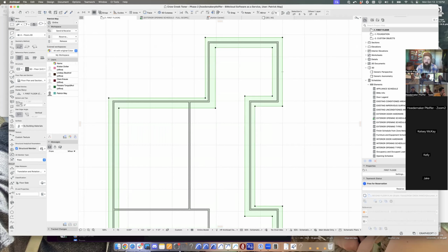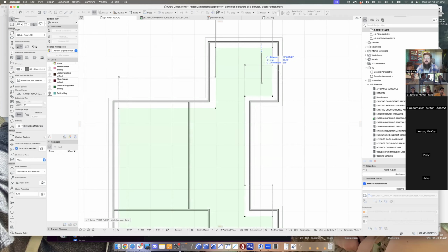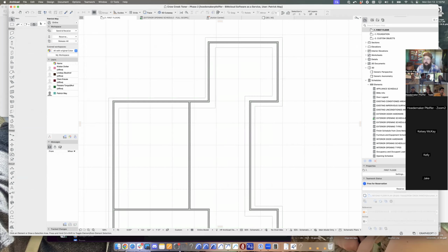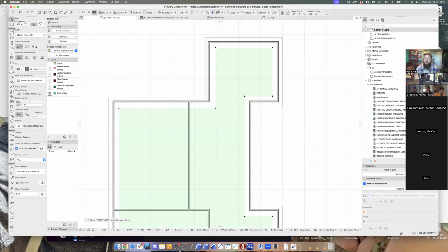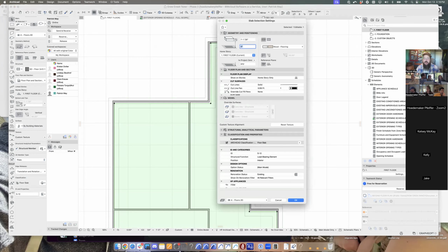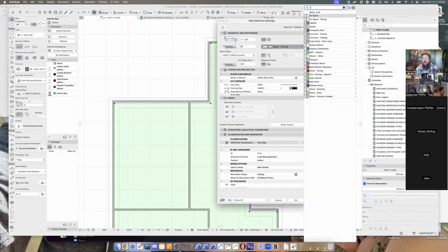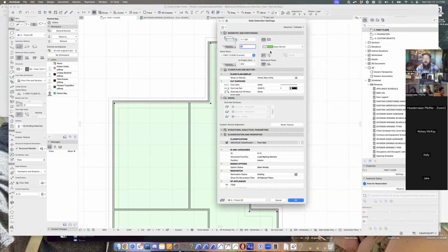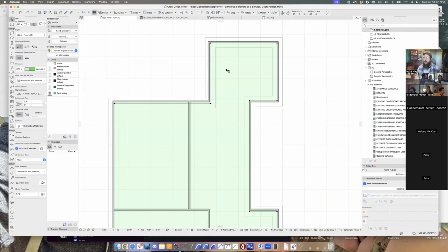You have to delete that inner one still, right? Correct, yeah. So I select that inner piece right there and just delete it. Or, a lot of times actually what I'll do is I'll offset the inner area back out and then change its settings to be like a vapor barrier that's like 1/16 of an inch thick. And then that becomes my operator to trim out my site mesh. So yeah, you can keep that extra thing, and if we look at those together.